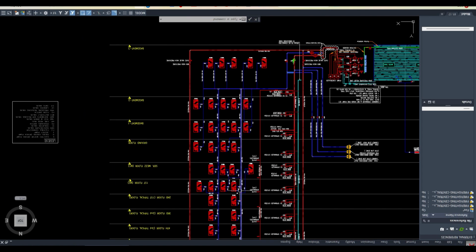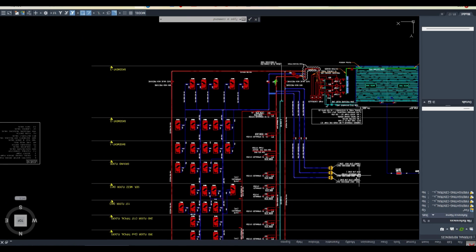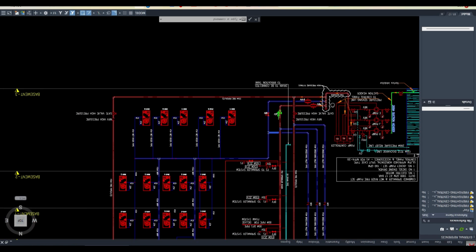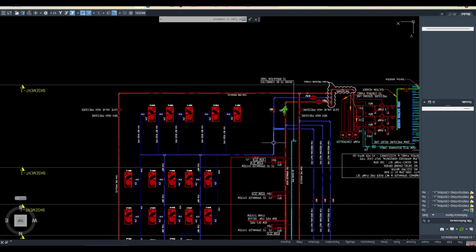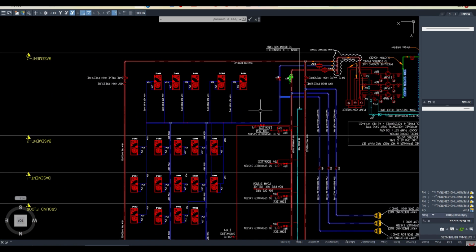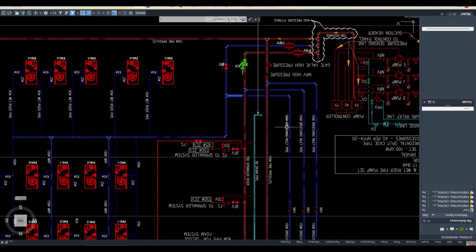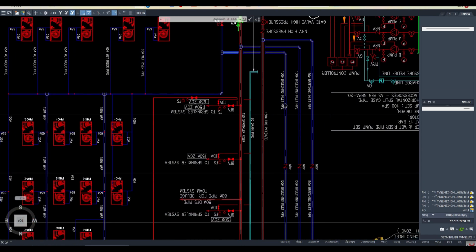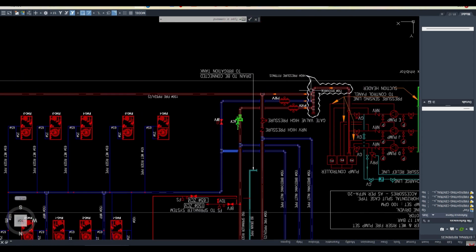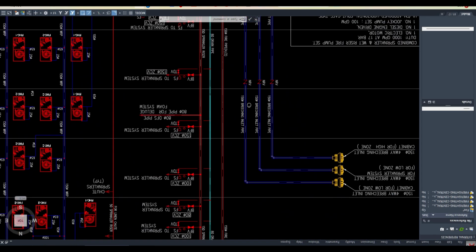Okay, so what's happening, we have the backup system. Either they can directly operate it from the fire truck, or they can operate it from the pumping station, whichever is working. So it's just like a backup system. That's why one breaching inlet also should be connected with this pipe, after the pumping system. So that is it, this one.